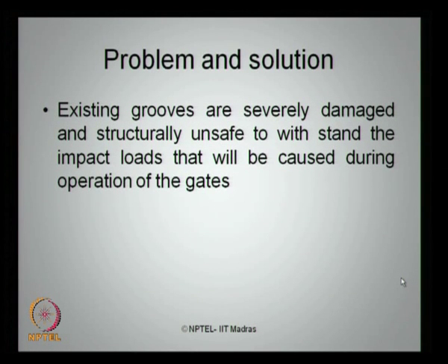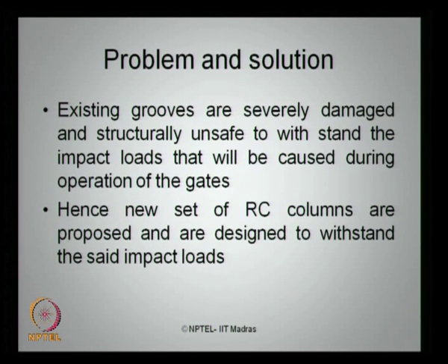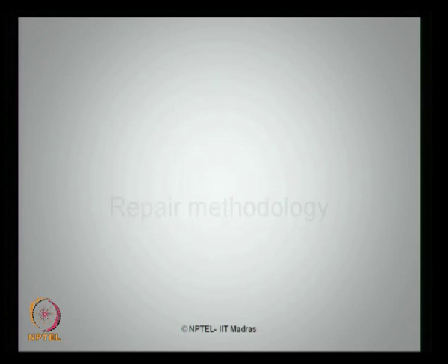So, the problem you just saw is that the existing grooves are severely damaged and seem to be structurally unsafe because they cannot withstand the impact loads which are posed by the gate when the gate is under operation. Hence, a new set of reinforced concrete columns are proposed in the design, and they are designed to withstand the said impact loads caused by the gates.